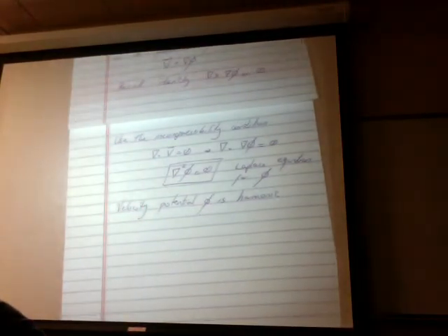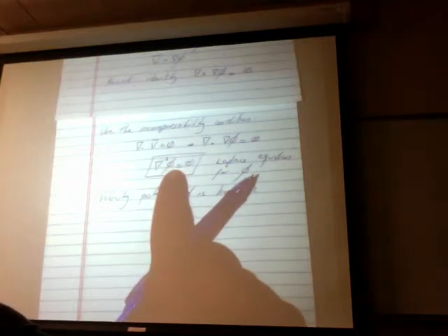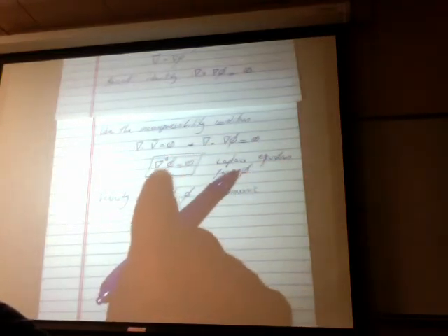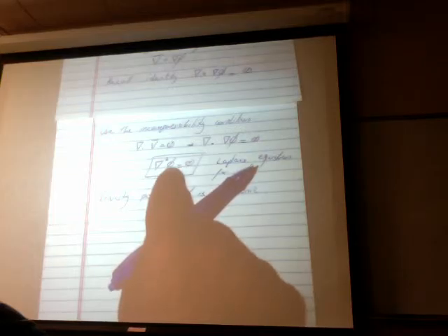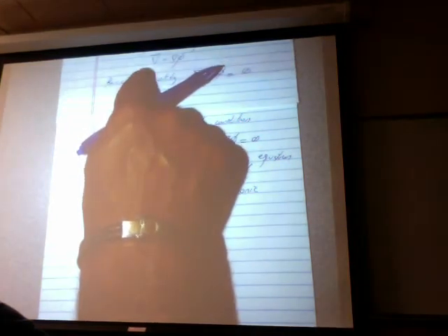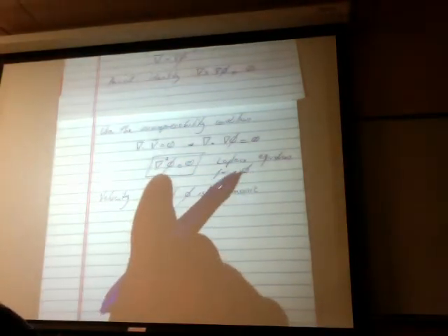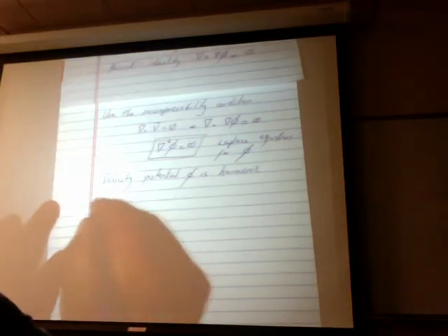All right. So now instead of trying to solve the continuity equation and the Navier-Stokes equation, we can just try to solve the Laplace equation for phi under certain boundary conditions and constraints. We solve the Laplace equation, we find phi, and with phi we construct v, because v is the gradient of phi. Right? It makes it easier because this is a linear equation. It's well known, it's well posed, and there are many analytical methods to solve that equation. Okay.